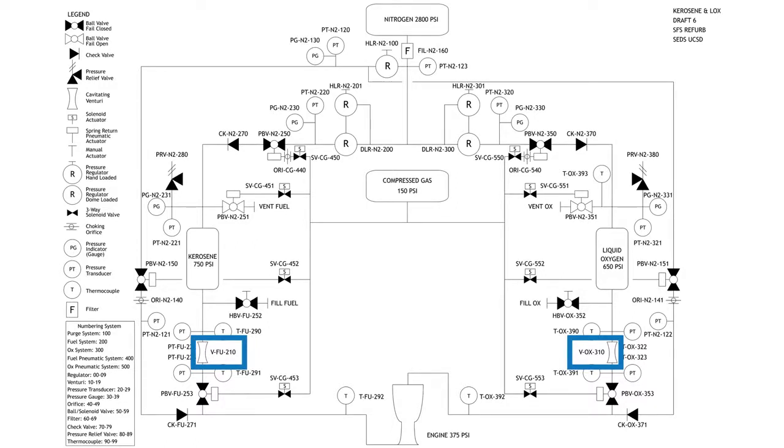And I say trickle, but it's really flowing really fast. So with that, we're going to be able to tell exactly what goes into that Venturi and what comes out of that Venturi. And the way you design these is if you have a 15% pressure drop across it, so if you have 100 psi and you drop down to 85 psi, then you can use a certain set of equations called the cavitating flow equations to know exactly what your flow rates are.